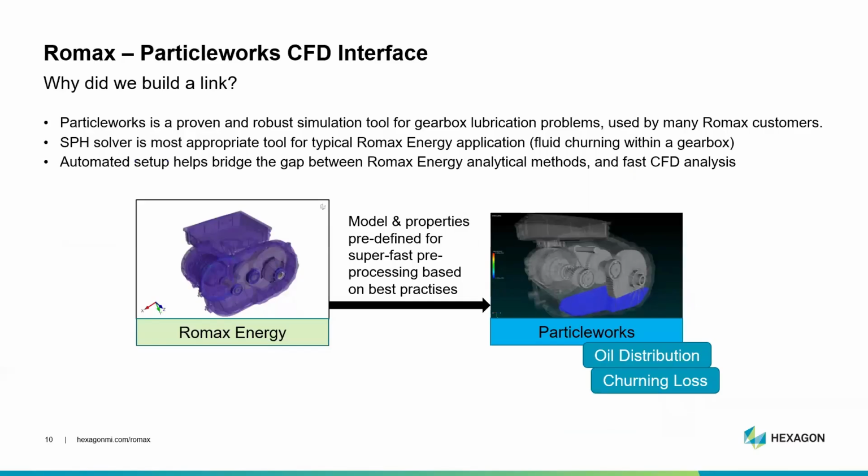So, the link between Romax and Particleworks, why have we done it? Well, as Didier was saying, Particleworks, it's a proven and robust simulation tool, and one of its many capabilities is for gearbox lubrication problems. The SPH method is the most appropriate capability for the typical Romax Energy end user, typical problem being fluids churning within a gearbox. And by building an automated setup, we've helped to bridge the gap between Romax's analytical methods and a fast CFD analysis.